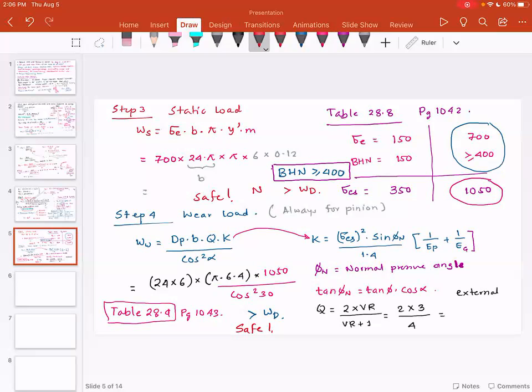So when you want Brinell hardness number to be greater than 400, you need to have special purpose heat treatment and annealing processes to make sure that that part is uniformly hardened, and you are going to ensure the case hardness is equal to the core hardness. So that is expensive.